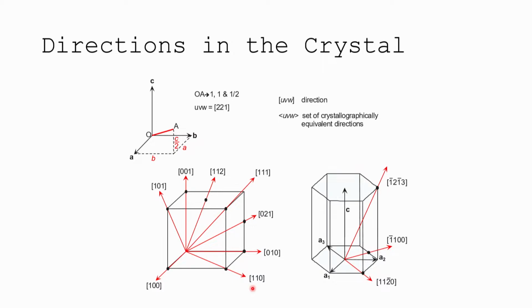All right. Miller indices, right? From your very first material science class ever, assuming you've had these, you've done Miller indices. So you have a lattice or a crystal structure defined by these lattice constants A, B, C. And then you have some direction, and you can define that by these intercepts to the lattices, which are going to be A and B, and then C over 2. So you basically have 1 in A that is coming out, 1 in B that is coming out, and half in C that is coming up. Okay? So you have 1, 1, and a half.